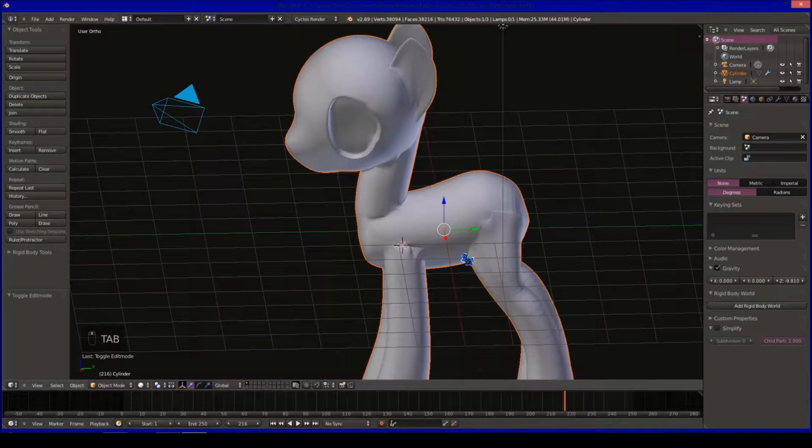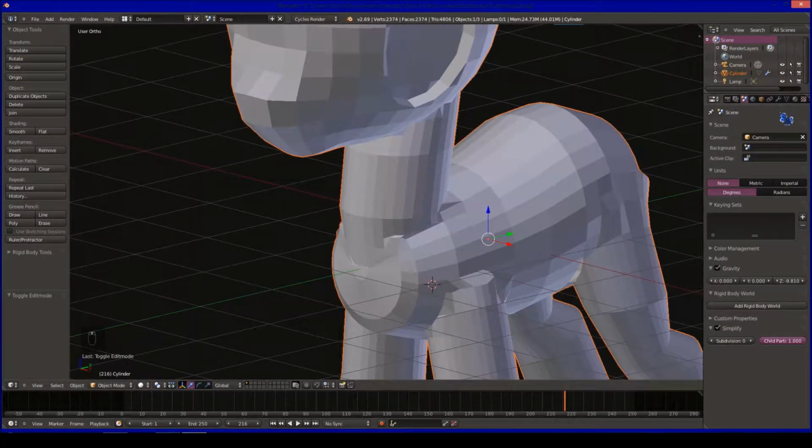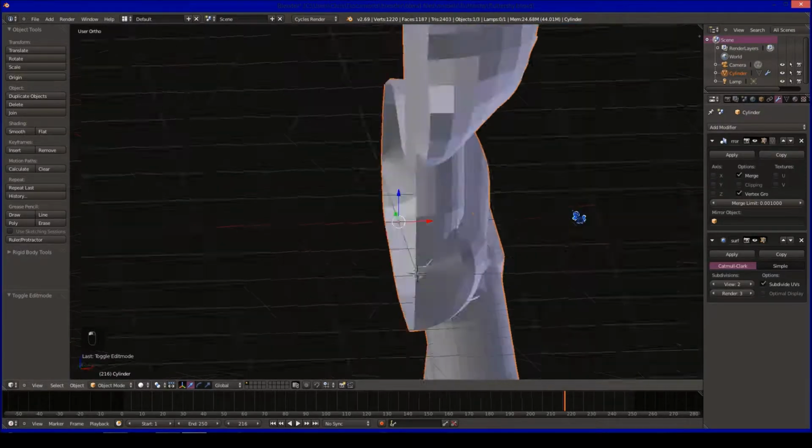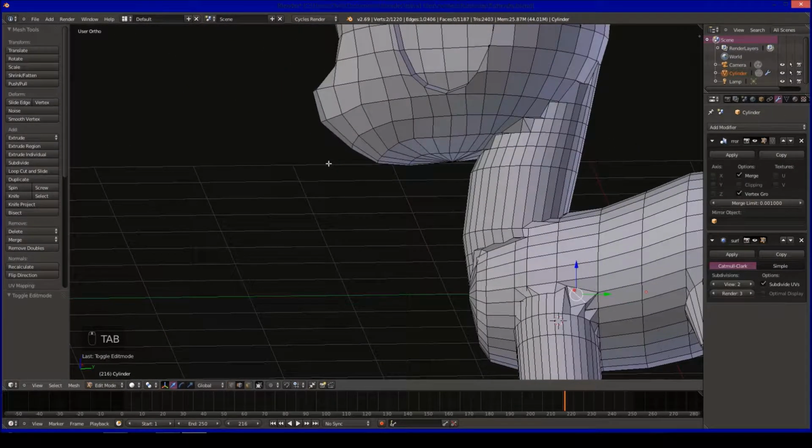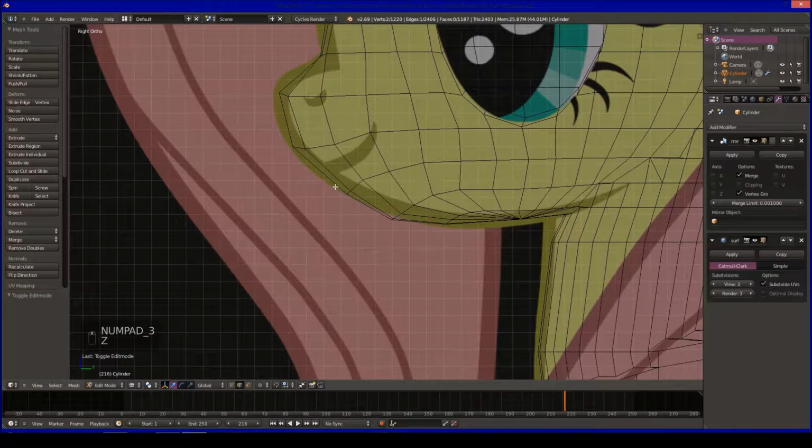So it's not really going to work, but if your model's moving around, it cannot handle it. At least mine can't. So I'm going to go ahead and leave this thing simplified. I'm going to go back to our modifiers, uncheck x-axis mirroring, and tab back into edit mode, and what do you say we actually do a mouth?